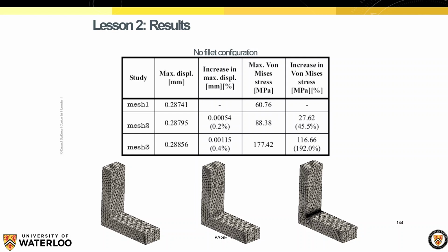If you're bending this and pushing down, the bending moment goes up. If you remember from the solid mechanics class, the bending moment will go up as you go closer to the wall. So theoretically, you're going to get a higher and higher amount of stress as you go closer to the edge.